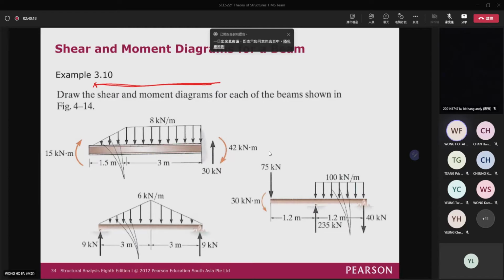And then you can see that the distributed load is negative because pointing downward is negative. It is 0 and then negative, more negative, very negative, and becomes a constant negative value here. So you can see that the slope becomes larger and larger when we go to the right-hand side, okay? And then the value is a constant afterward.